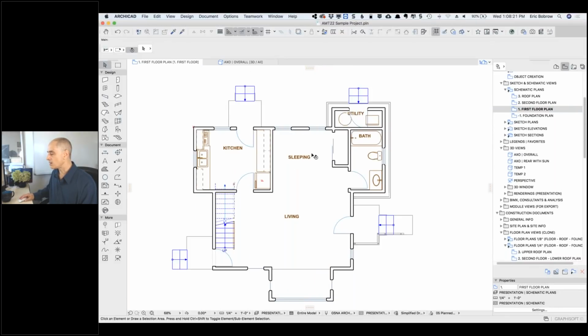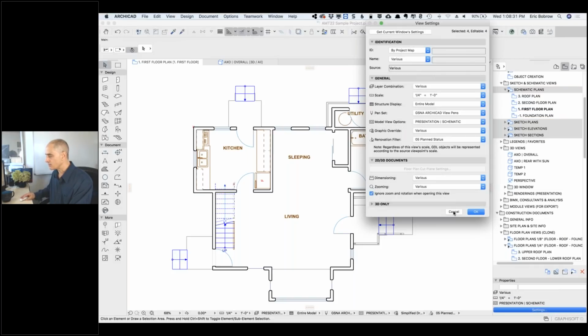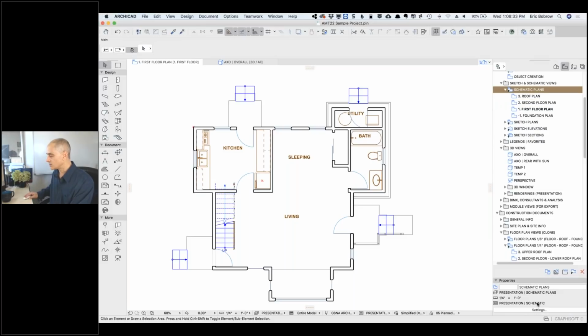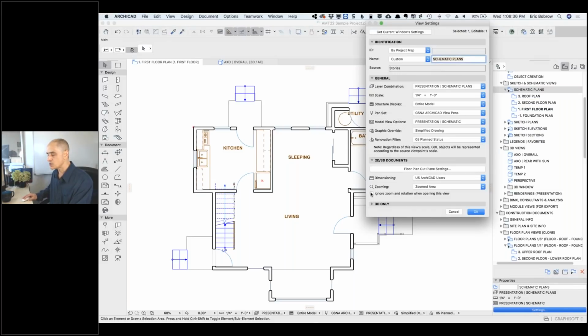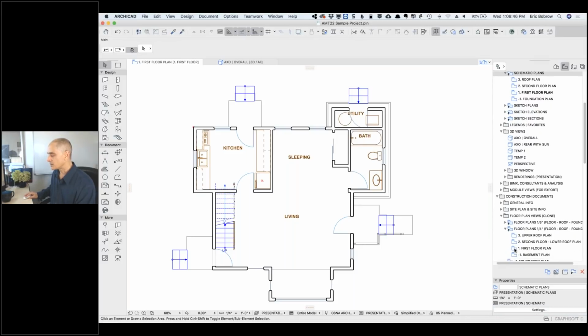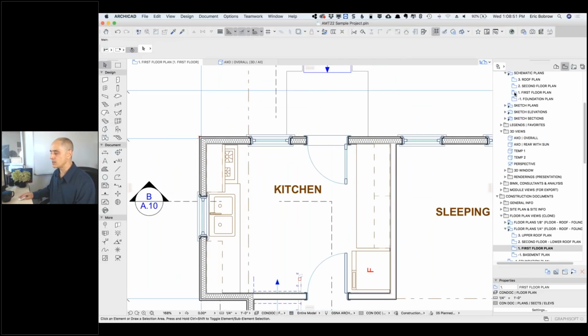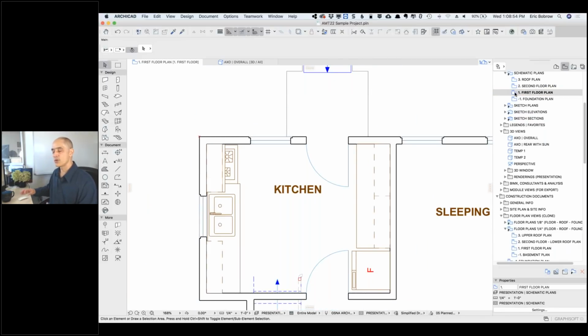Now, how is this accomplished here? And I'm going to basically change a setting for all of these so that they ignore the zoom. Actually, so let's see if I ignore here this settings for ignore zoom. What that'll mean is that if I come in and out of it, it won't jump me to a new position like this was. So we'll say ignore zoom. So now if I'm in here and I go back to this view here, I can switch between this view and the other view without having it jump around. Makes it much easier to see what's going on.